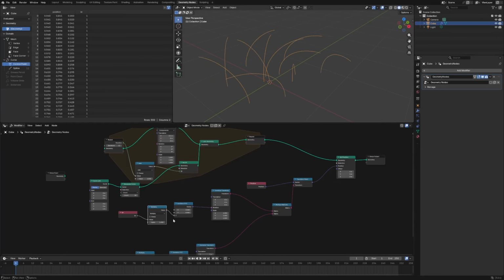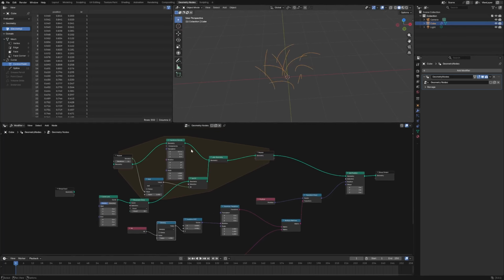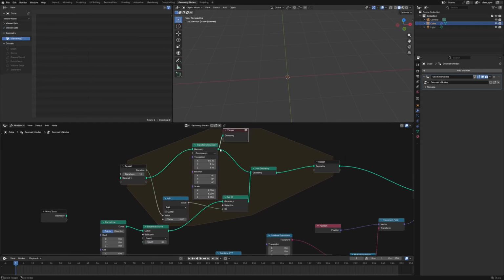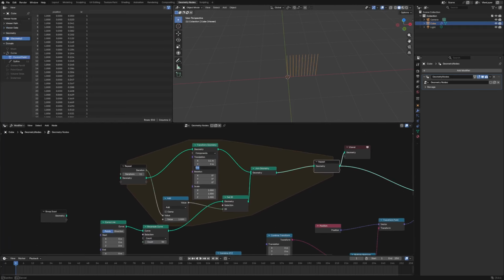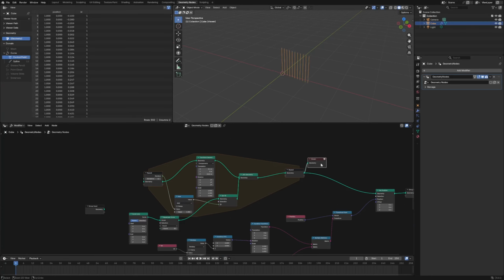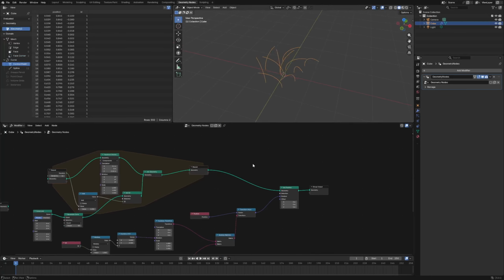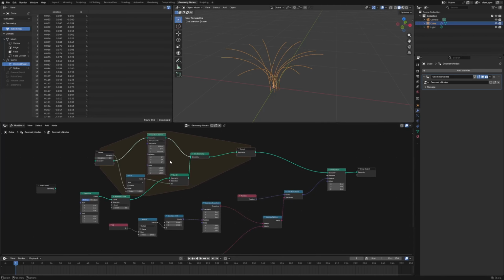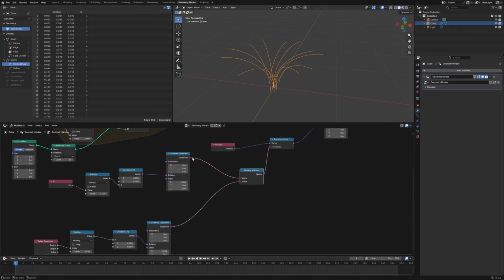So that's why we're getting the spiral when we're literally just doing a really simple repeat zone with this transform geometry to define it. And we even probably could do a minus 0.01 or so. Now it's going down a little bit too. So looking at all of this, it's going down. So now we're getting this spiral really easily with just a couple nodes inside this repeat zone. It's really an easy way of making dynamic spirals with the multiply matrices nodes and the combine transform.